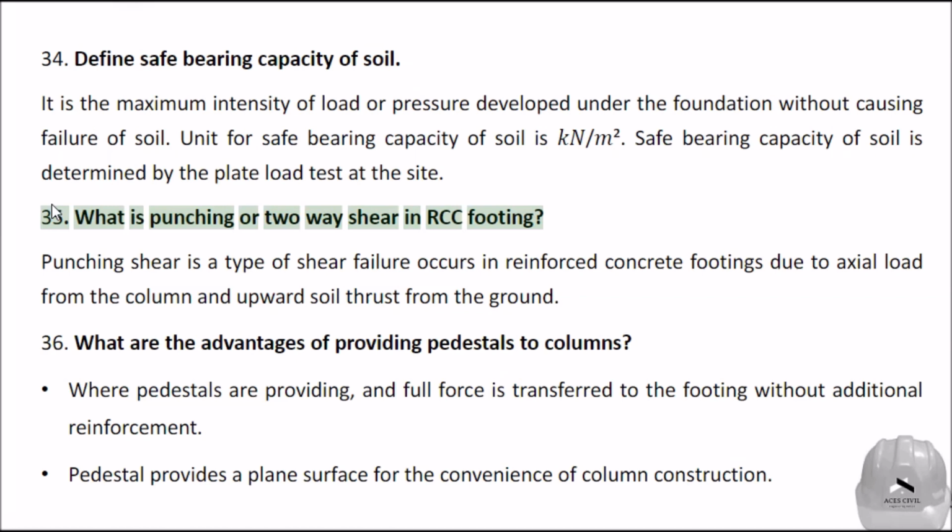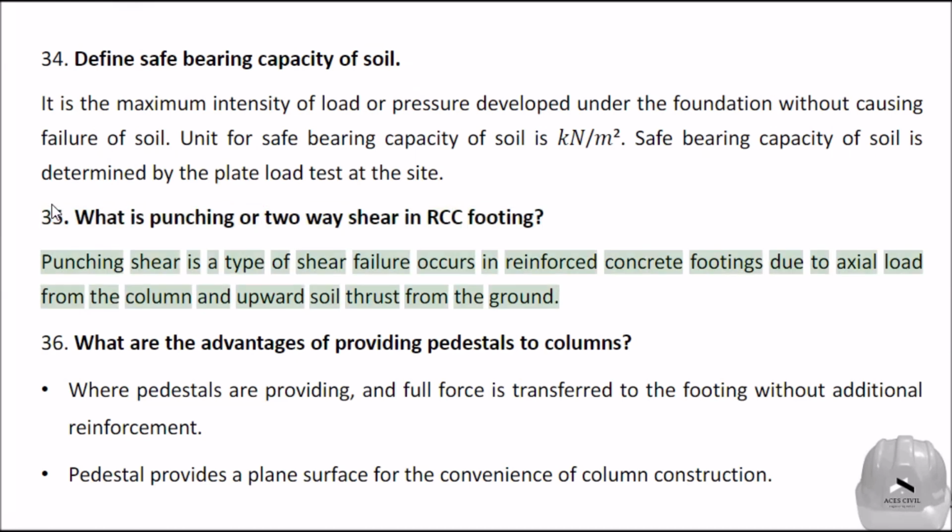What is punching or two-way shear in RCC footing? Punching shear is a type of shear failure that occurs in reinforced concrete footings due to axial load from the column and upward soil thrust from the ground.